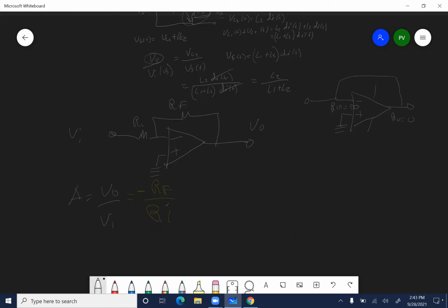Well, you have to understand a little bit about the op amp. I gave you one hint already: what is the input impedance to an op amp? This is infinite here, right? So how much current can go in here? 0. So all the current that goes here has to go here, right? Any current that goes there has to pass through there. It can't go in that direction. Ultimately, what we're focused on is that no current can go in, so let's not even include this part. We don't even need this part.